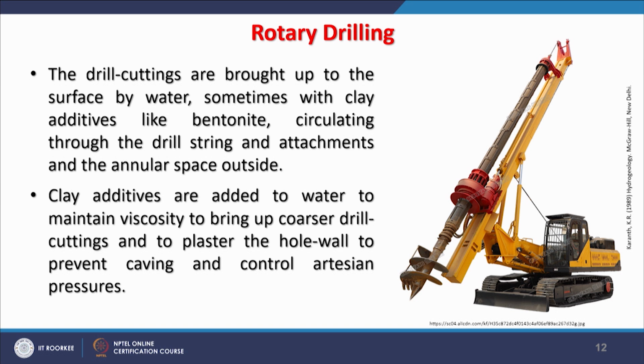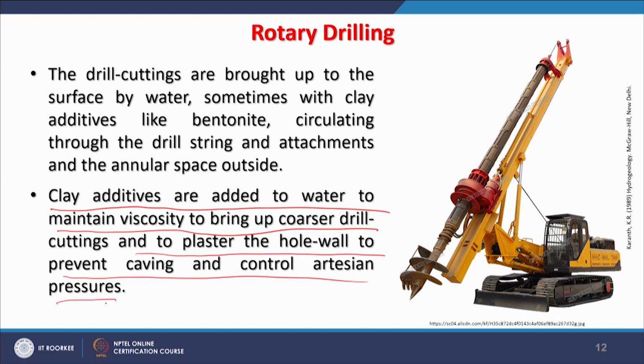Clay additives are added to water to maintain the viscosity, to bring up the coarser drilling cuttings or rock pieces, to plaster the whole wall, prevent caving and control artesian pressure. So, this mud in hydraulic rotary drilling does two kinds of services.